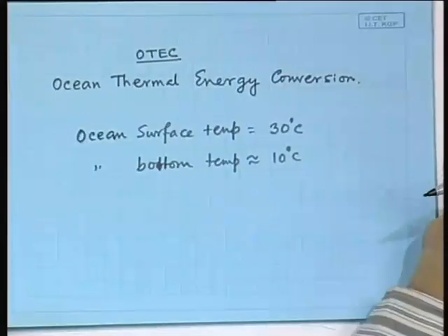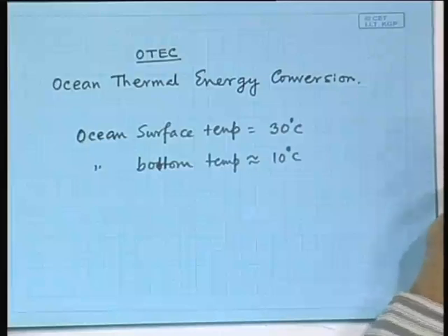But you do not have a calculator, you can simply press and tell me the result. 8%. How did you get it? So, 1 minus T2 by T1 in absolute scale. This has to be converted into absolute scale, and then only you can talk about the value. So, how much is it? 3.3, something like that. Is it right?